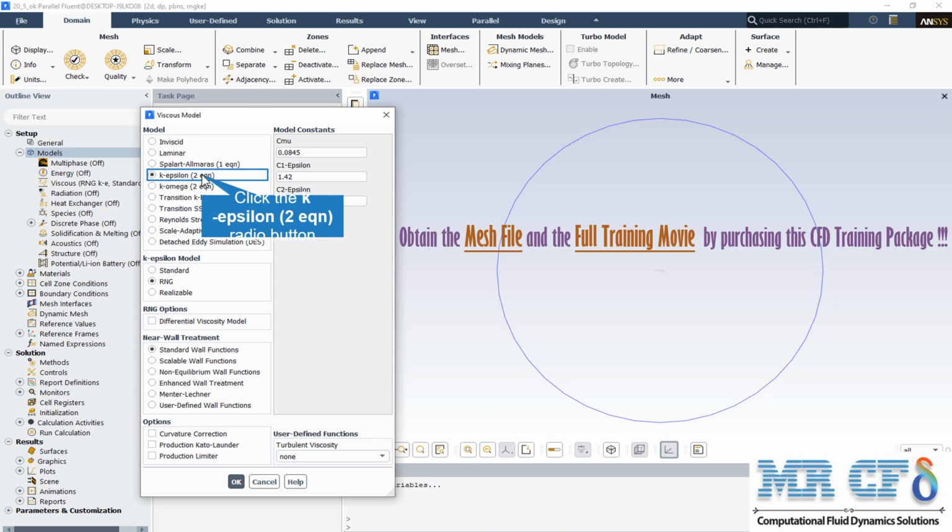The RNG K-epsilon model is derived using a statistical technique called the renormalization group theory. It is similar in form to the standard K-epsilon model, but includes some refinements. For example, the RNG model has an additional term in its epsilon equation that improves the accuracy of rapidly strained flows. Also, the effect of swirl or turbulence is included in the RNG model, enhancing accuracy for swirling flows.